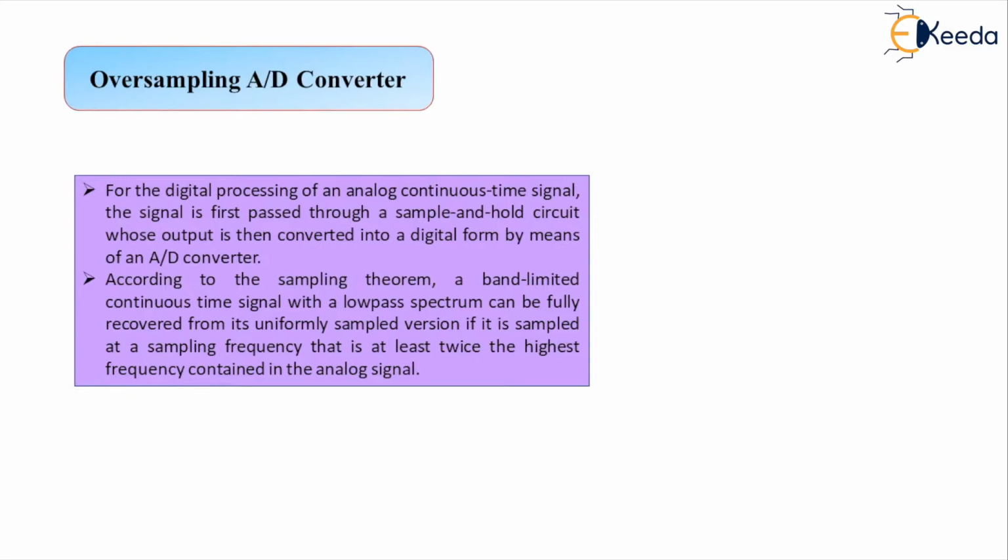See, if this condition is not satisfied while designing the communication system for digital data, the original continuous time signal cannot be recovered at the receiver end by using its sampled version because of the aliasing effect. Now, we don't want any aliasing to occur practically, and therefore the analog signal is first of all passed through an analog anti-aliasing low pass filter, which is the section prior to the sampling process that also enforces the condition of the sampling theorem.